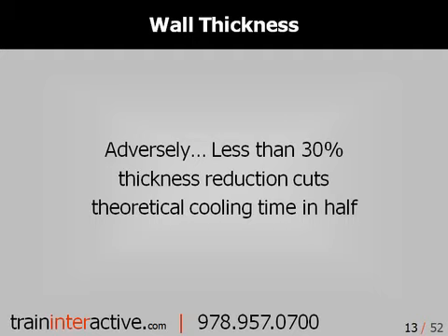Additionally, a part with reduced thickness will fill faster, require less packing, and consume less material, thus saving time, energy, and resources.